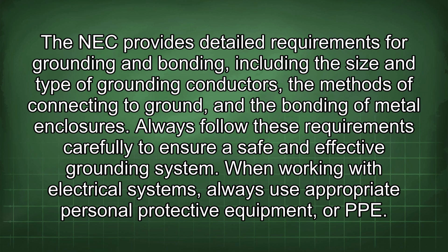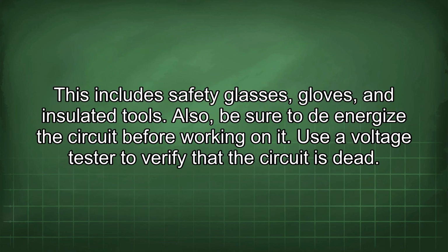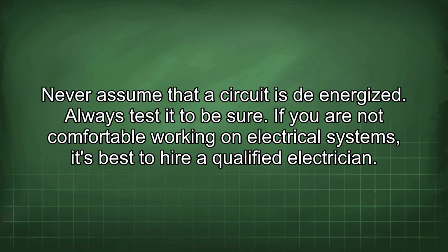When working with electrical systems, always use appropriate personal protective equipment, or PPE. This includes safety glasses, gloves, and insulated tools. Also, be sure to de-energize the circuit before working on it. Use a voltage tester to verify that the circuit is dead. Never assume that a circuit is de-energized. Always test it to be sure.